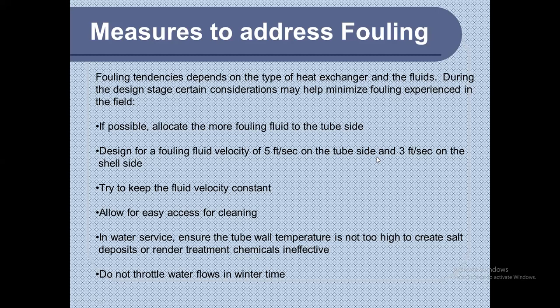That's about the definition. Okay, a simple case of throttling is that you decrease the flow, or there is going to be a restriction in the flow from higher cross-sectional area to lower cross-sectional area. That's throttling. And in the process of throttling, of course, there's going to be a pressure drop, or a change in the flow pressure. So, Mel has given us the definition of throttling.